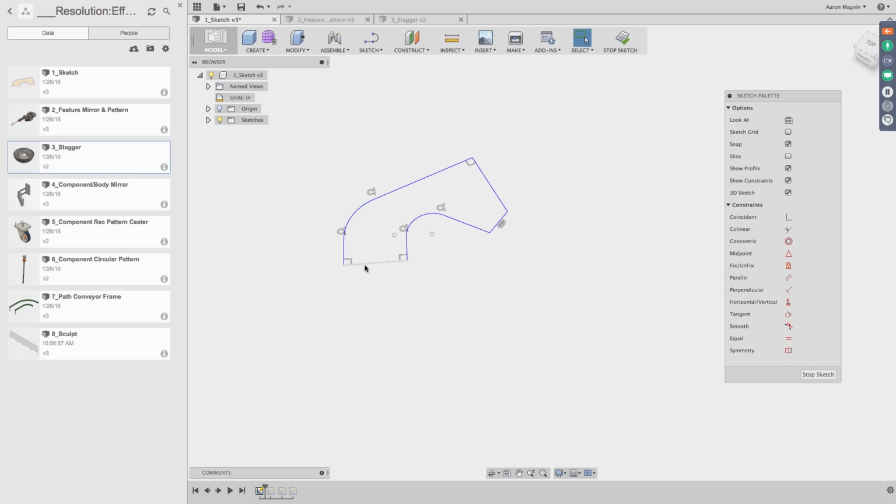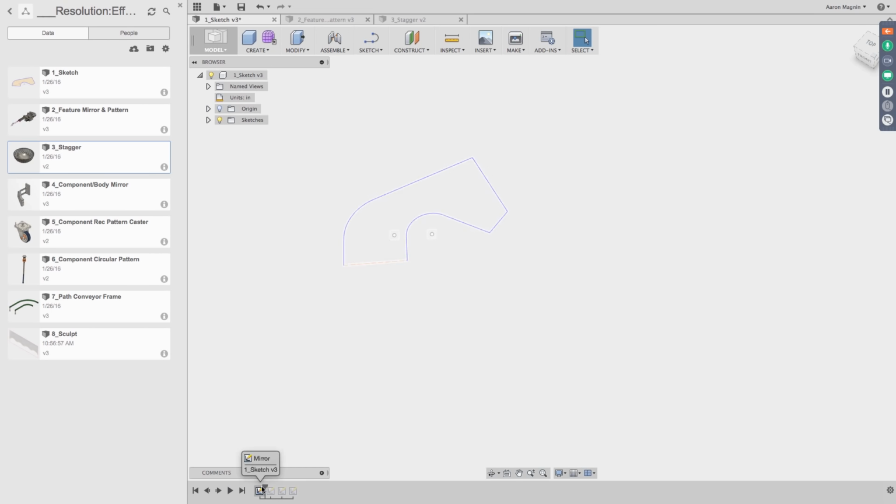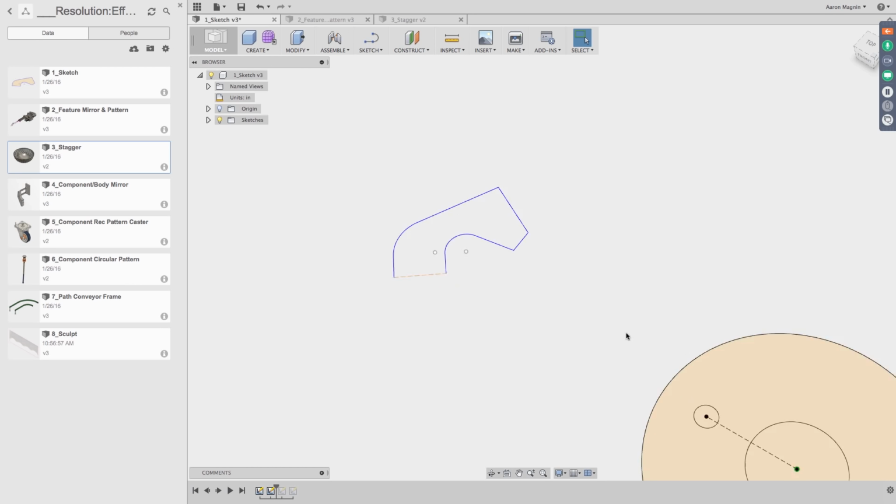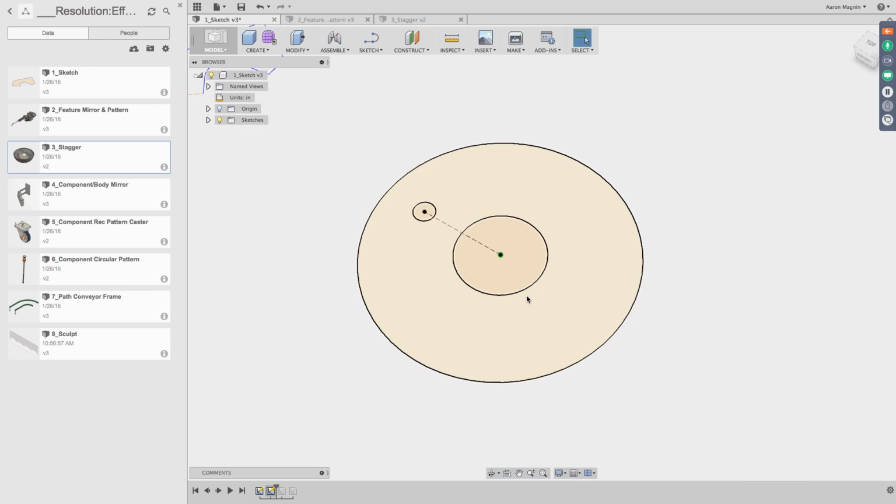It's showing me that it's kind of a dashed line, and actually, because it's not a completely closed profile anymore, it's not actually showing me that shaded view anymore. So that might help you to convert lines into construction geometry a little bit easier and get through that a little bit faster. But just like that, that's your approach that you're going to use to do mirrored sketch entities.